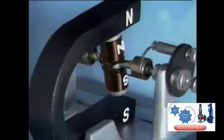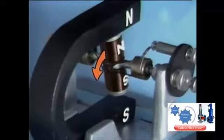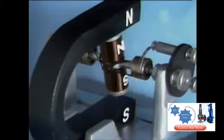When the rotor is in this position, the north pole of the rotor is repelled by the north pole of the stator and attracted by the south pole of the stator. Similarly, the south pole of the rotor is repelled by the south pole of the stator and attracted by the north pole. The combined effect of these attractions and repulsions moves the rotor.